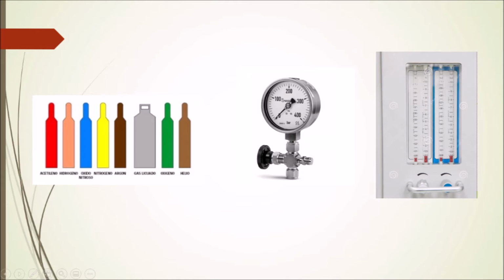The flow of each gas is a continuous flow unit, controlled by a valve and indicated by a flow meter. The flow meter can be a purely mechanical arrangement with a flow tube in which a coil moves up and down depending on the flow, or it can be an electronic sensor with an LCD screen. After the gases pass through the control valve and flow meter, they enter the low pressure system and, if necessary, pass through a vaporizer, and are then administered to the patient.